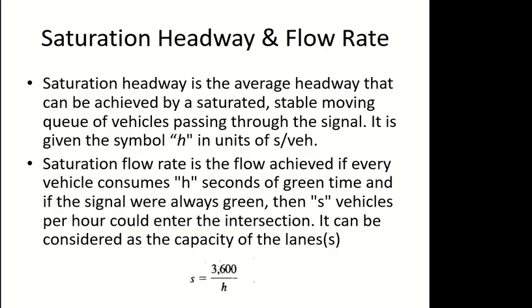Headway is the inverse of flow rate, again something which we discussed in the first chapter. So when you take the inverse of minimum headway, it becomes saturation flow rate. Minimum headway is saturation headway, right? So when you take the inverse of saturation headway, you get saturation flow rate. The general relationship is that the inverse of headway gives me flow rate, and the inverse of saturation headway gives me saturation flow rate.